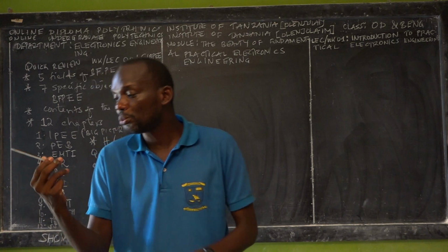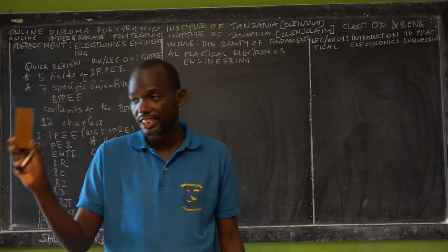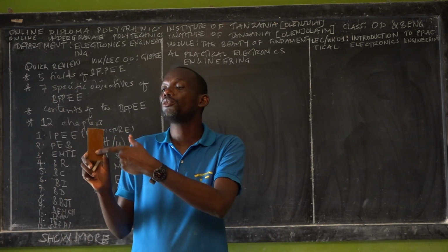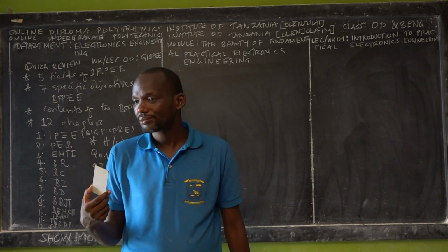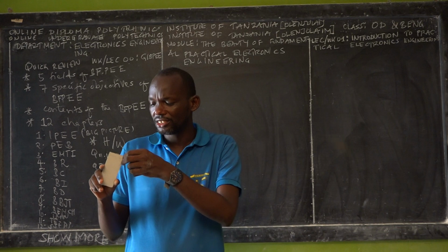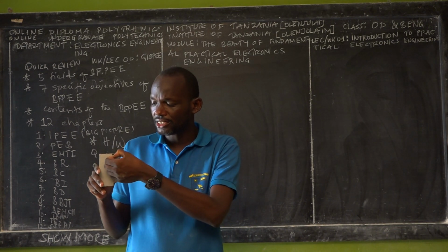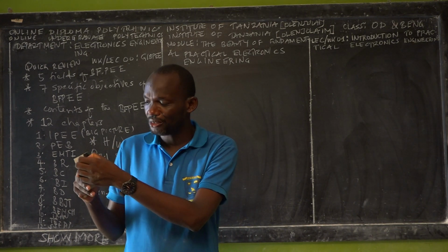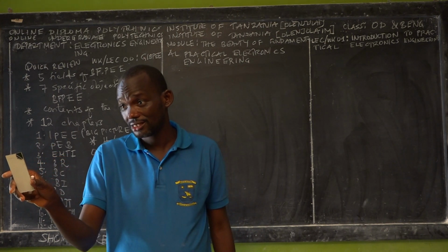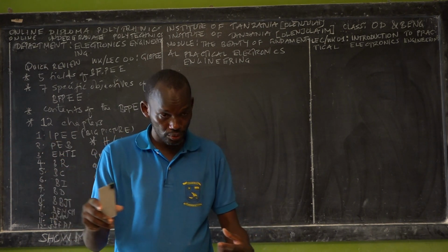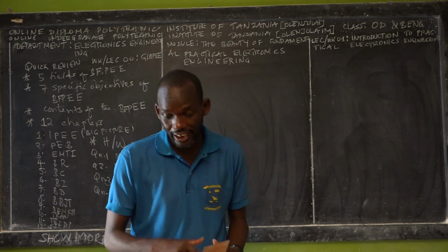This PCB board has 2 sides. It is a single-sided board because on top of it it's plastic, but at the bottom it's copper. But this copper has been protected. For example, if you take this one, you see the greenish layer. That greenish is a chemical substance, and you actually have to do an etching process until you have a circuit like this one.